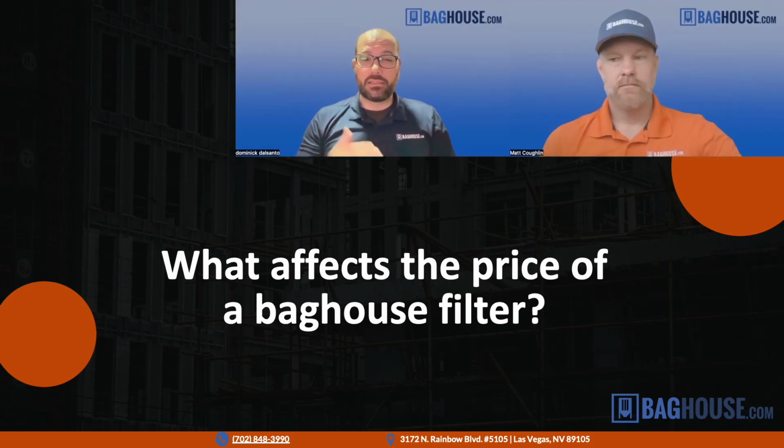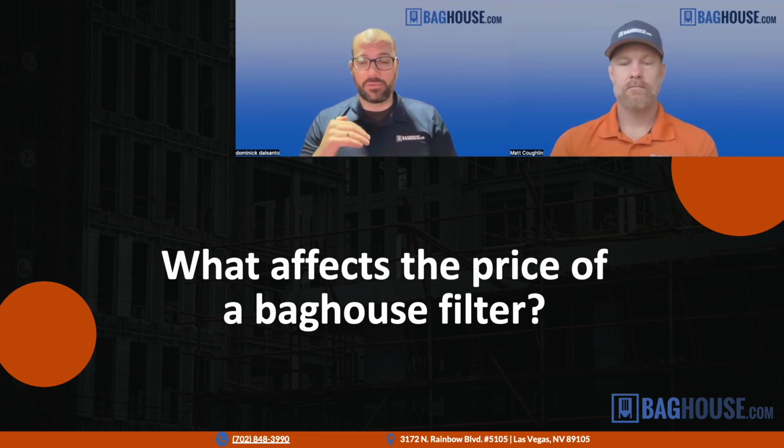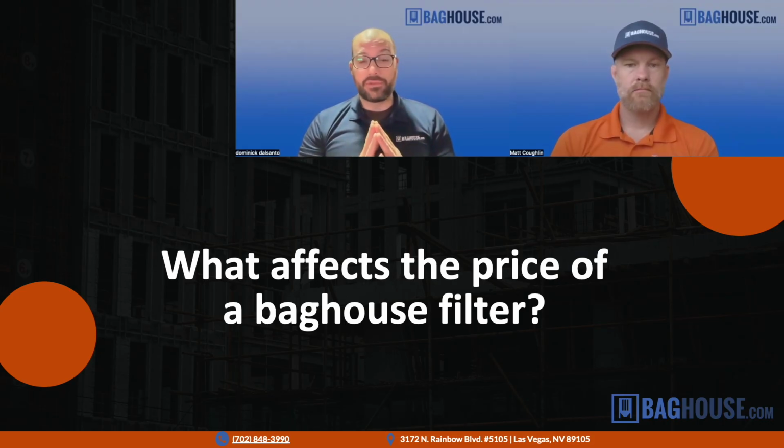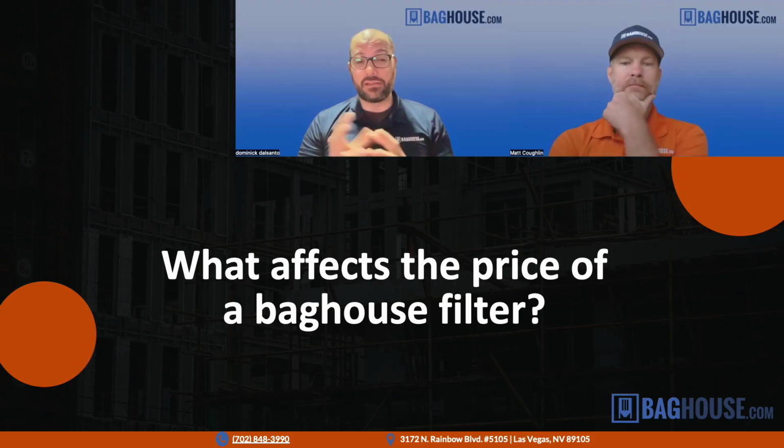So we always say there's a list of things when we're considering what filters to use. What's the temperature is the first one, followed by what kind of dust you're collecting, followed by what kind of chemicals are taking place in the process. And the last one is the price. So we divide everything first into temperature. So is the process about 260 Fahrenheit or less?